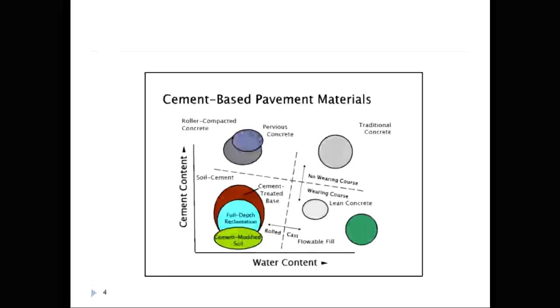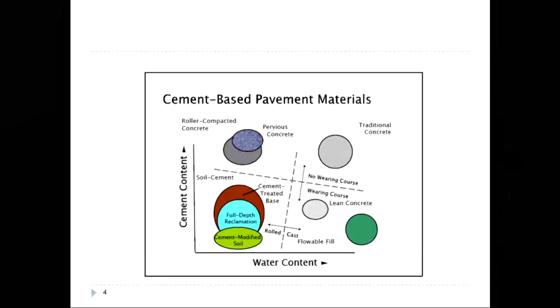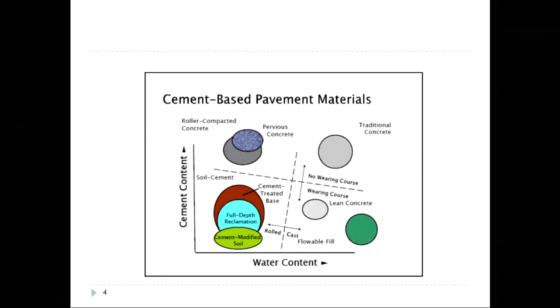In the case of sub base layers, you would have been using a cement content of the order of 3 to 4%. In the case of cementitious base layers, you would have been going for cement contents of the order of say 6 to 7%. If you look at the water content of your cement treated sub base and base layers, you would have adopted a water content close to the optimum moisture content of the mixture.